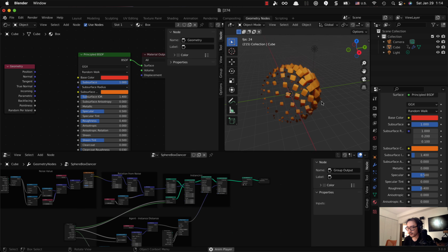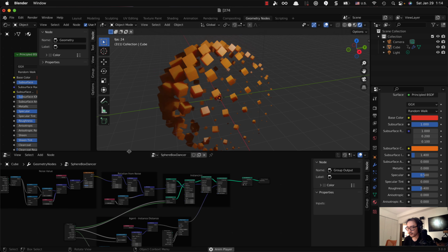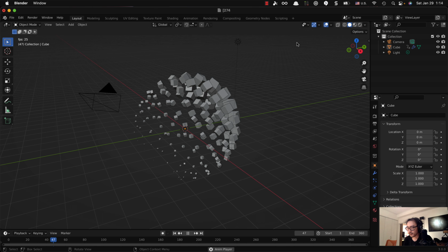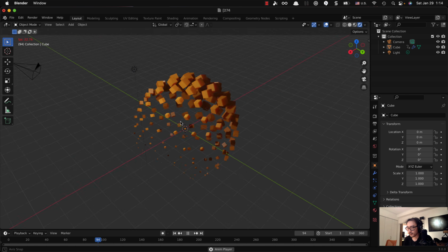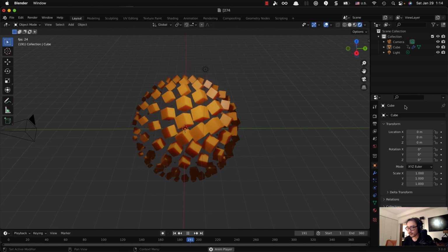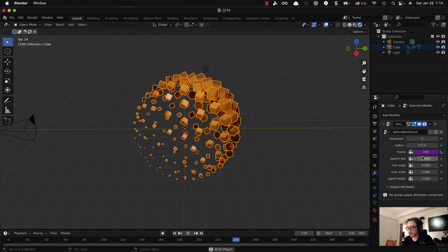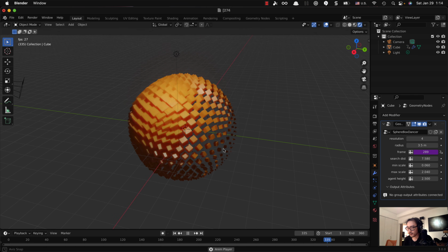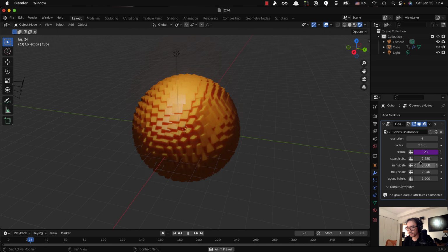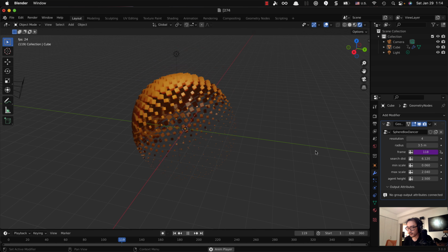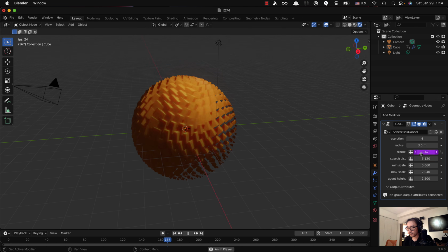And what I want to do now is to set up some lighting for this. So let's go to the layout, show up the render view, and let's set up some parameters first. Let's make the resolution 4. Okay, and search radius a bit smaller, like that.